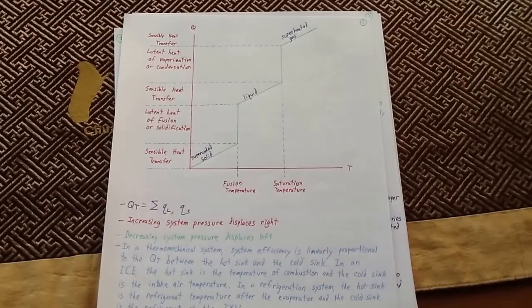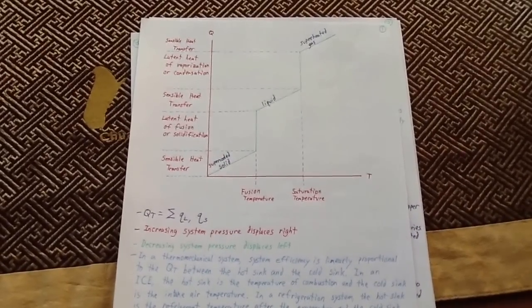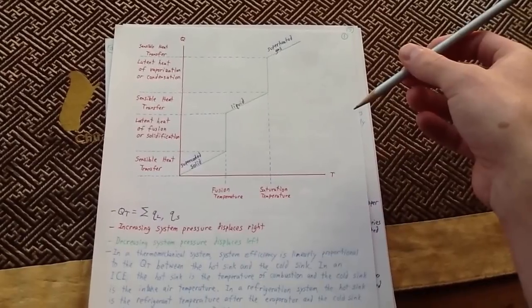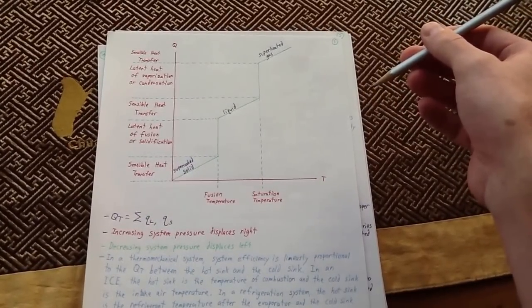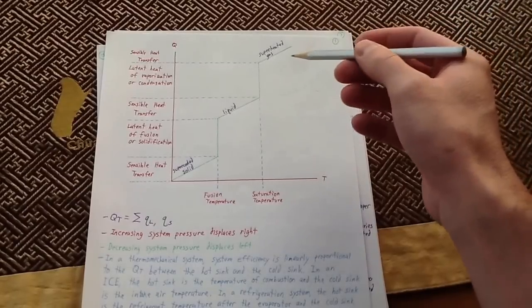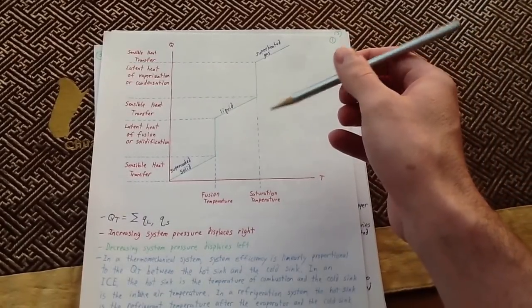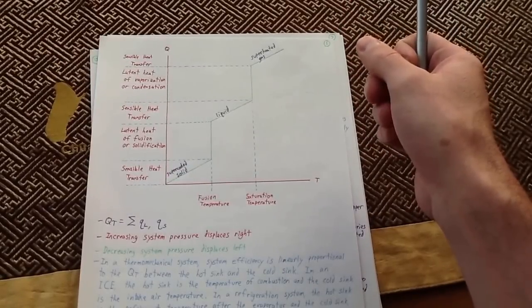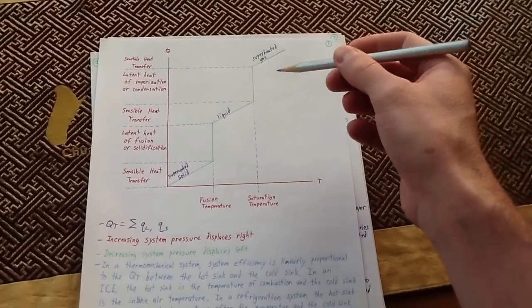Consequently, the liquid water in there can't transform into a gas. Because of that, you can actually have water that is higher than 100 degrees Celsius and it remains in a liquid state. You might actually have it at, say, 200 or 300 degrees Celsius, and it can't transform into steam because you are adding that pressure, and the molecules can't expand and it can't transform into a gas.